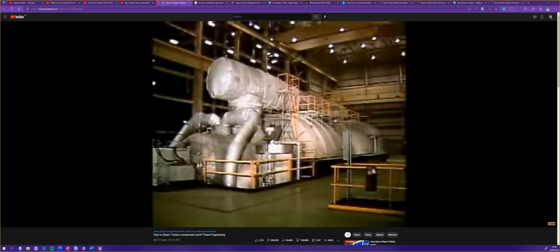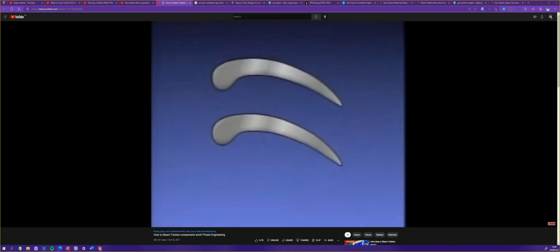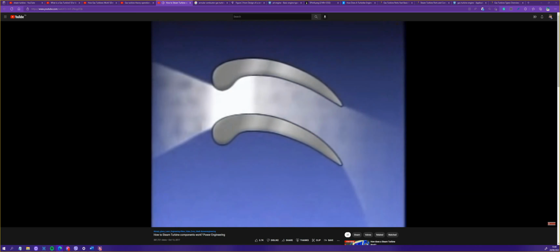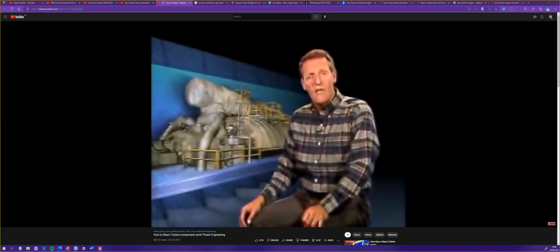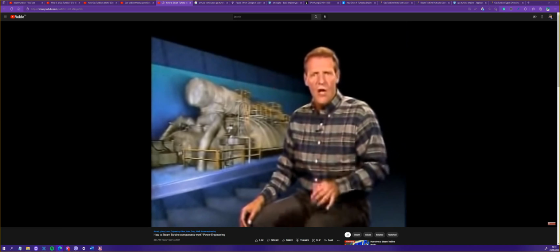In a turbine, the moving reaction blades act like the nozzle in a rocket engine. Steam leaves the blades at high speed and creates a reaction force on the blades, and that causes the wheels to turn the turbine shaft. Most modern turbines combine the use of impulse blades and reaction blades to make the most efficient use of the energy in steam.